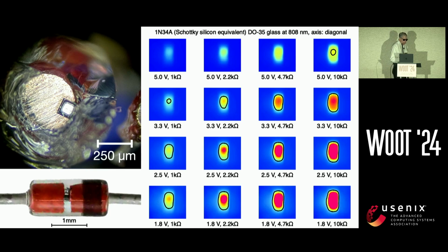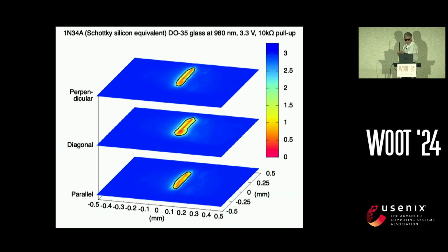By the way, unlike LEDs, which tend to respond to visible wavelengths, we found that the most effective wavelength for silicon devices, ESD protection devices, is in the 900 nanometer range, which means it's invisible. That makes the attack stealthy. It's not isotropic either. This figure shows the effect of elliptical beam axis rotation on the active area. We have not looked into the effect of polarization at all.